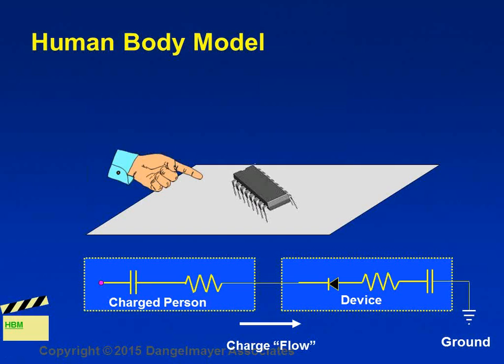if you were to stress a device that is not grounded, the HBM failure level would be appreciably higher than the test results from the industry standard tests, which is one of the reasons that we see less human body model failures. But the other is that most companies are doing an excellent job grounding people. And once you've done that, you have eliminated the human body model as a risk. So it makes sense that there are very few HBM failures today.